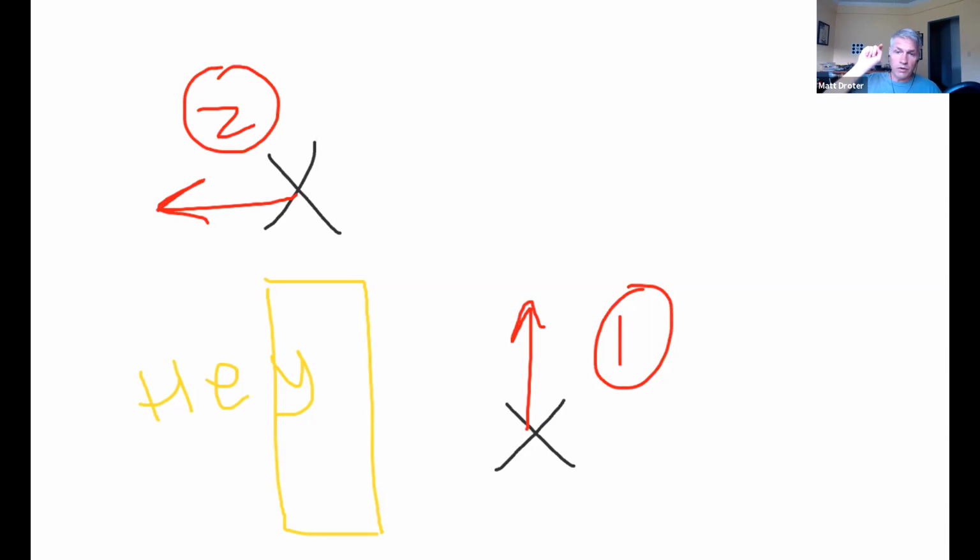So for example, when you click in RViz and you draw that arrow, you're sending 3 pieces of information. That's all it's doing. You're sending it X, Y, and yaw. And that's just an action server. So if you wanted to send in your own X, Y, yaw, MoveBase will take it. It's just sitting there listening. RViz has a little arrow, just makes it a little bit easier.